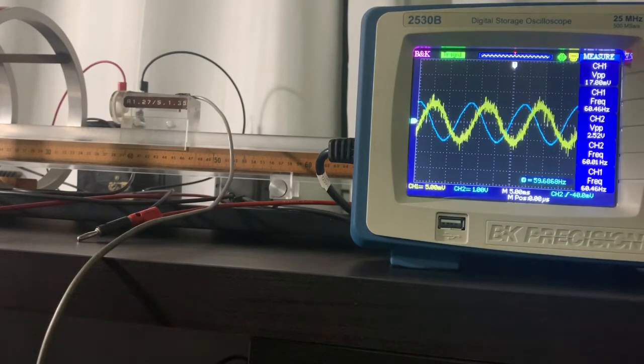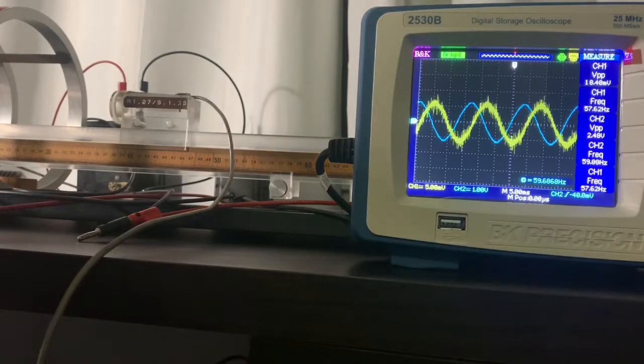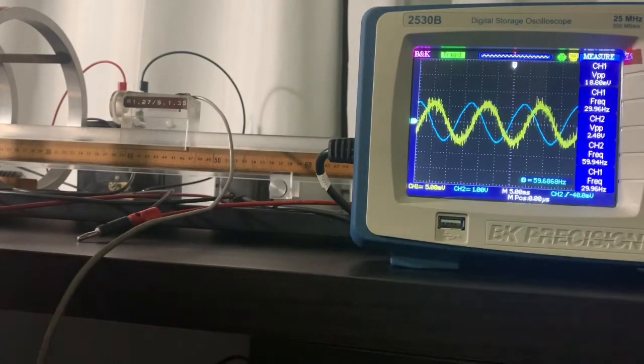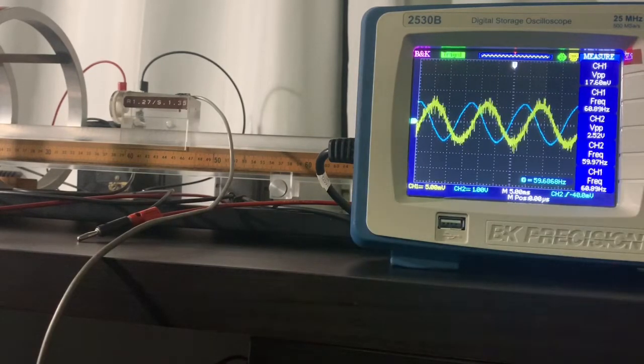And from now on, we're just going to rely on the oscilloscope to give us voltages and in effect the current going through this resistor. And for the duration of this part of the lab, we're not going to mess with that anymore. We know the current and we're going to keep it there. So in fact, you might want to make note of that. The max amplitude of the current going through that loop is 1.25 amps.